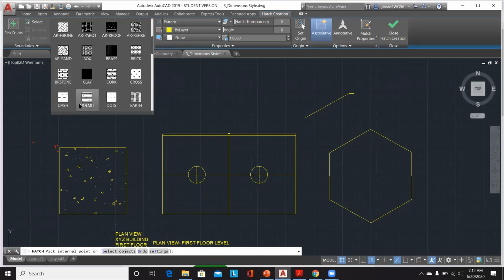When we are drawing plan views or floor plan views, everything looks similar because it is a series of rectangles and squares drawn in your modeling space. To distinguish between two model elements, you can use hatch and gradients to clearly identify them. We will discuss the purpose of these hatching and gradient tools when we cover detailed drawings in the clean and error-free drawings part, a few subtopics later.